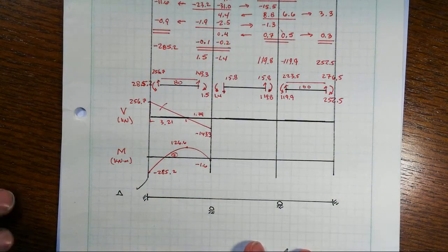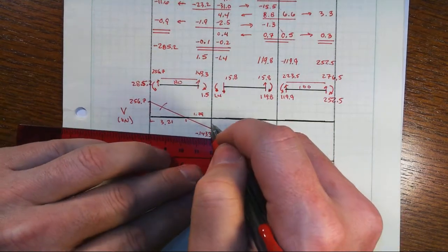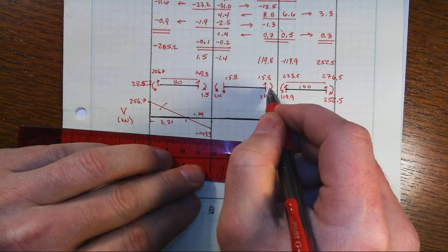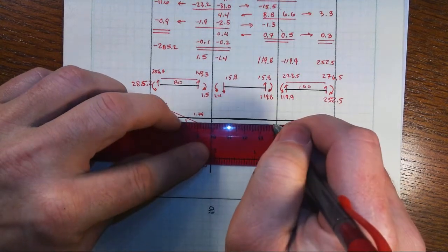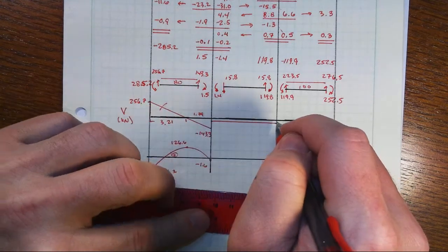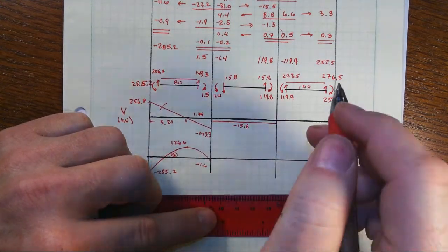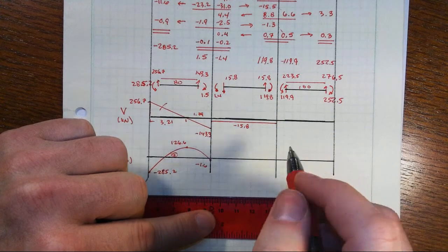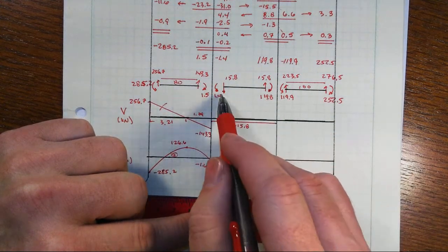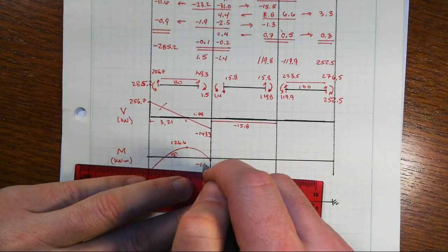Okay, that's that span. The next one's a little bit quicker to do. We go down 15.8 and then we'll come over flat at 15.8. So there really won't be much of a change here. Well, not much of one. There isn't any change on the shear diagram. And on the moment diagram, we'll go straight from the 1.4 or 1.6 or negative 1.5, whichever one you like